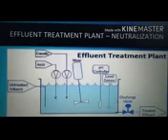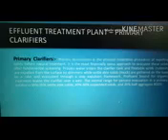So coming to the next, primary clarifiers. Primary clarification is the physical treatment process of removing solids before biological treatment. It is the most cost effective way to remove these solids after fundamental screening. Screened water enters the clarifier's tank and floatable solids, scum, are removed from the surface by skimmers, while settleable solids, sludge, are collected on the bottom by a rake and removed through a sludge removal system. Effluent bound for biological treatment leaves the clarifier over a weir.